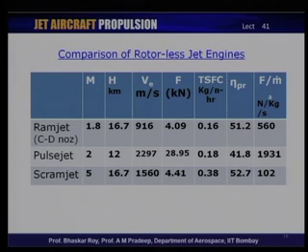These are, as I mentioned, the rotorless engines. That means there are no rotating parts, no compressors or turbines. So, these jet engines, when they are compared to each other, are all flying at supersonic Mach numbers at very high altitudes, and their exhaust velocities are all very high. And as we can see here, in a pulse jet engine, because of the high pressurization that is achieved in the combustion chamber, very high exhaust velocities are possible, as a result of which a very high thrust can be created. One can see here that the propulsive efficiency of the pulse jet engine is somewhat of a lower order.